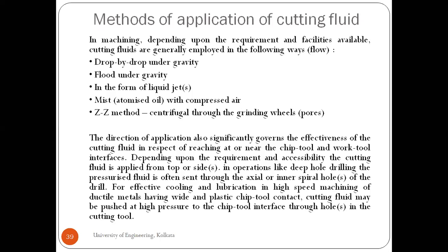So this is the distribution of the heat at the machining zone, and depending upon the requirement and accessibility of the cutting fluid, it is applied from top or side. In operations like deep hole drilling, pressurized fluid is often sent into the axial or inner spiral hole of the drill.